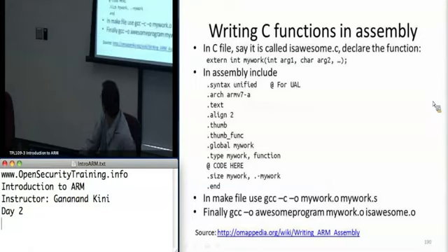All right. So now that we've done inline assembly, how do we reference direct assembly code in our C programs? As you've already seen, we can define our assembly function, which you already saw with Fibonacci. Generally, a lot of these directives are optional. Here, all I'm saying is the syntax is using unified assembly language, which is what ARM v7 follows.